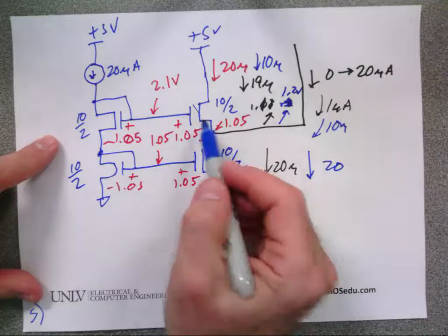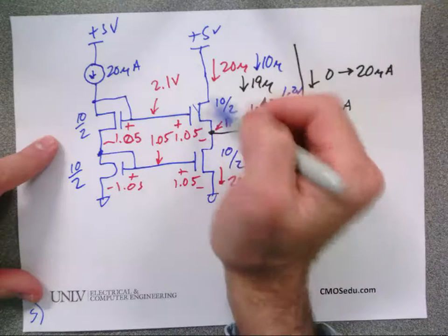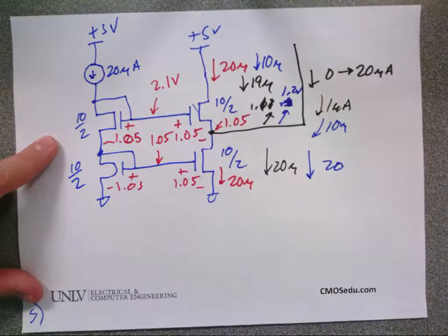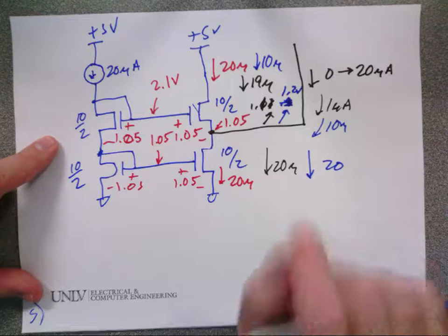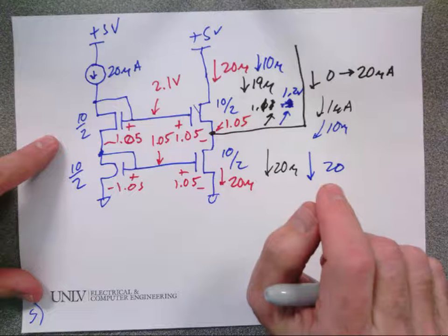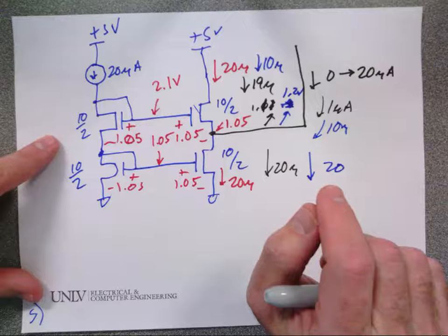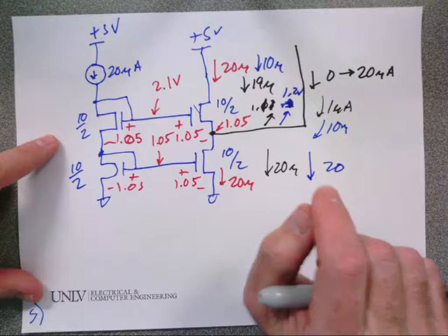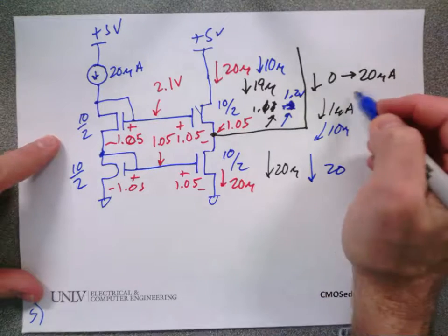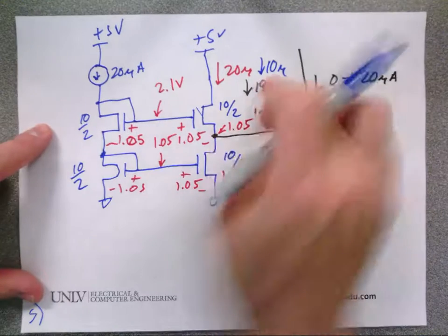No, because in the PMOS, the control is up here. Yep. So as you go to 20 microamps, this pressure goes up, shuts this guy off.